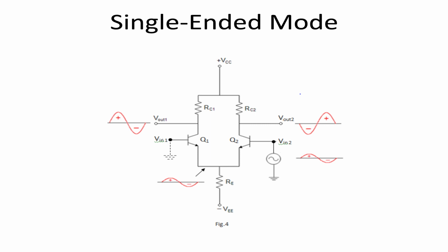The output is always equal to the multiplication of this capital A, that is the gain, and the difference between the inputs, given as V1 minus V2 or V2 minus V1, as we have two inputs at the op-amp. So, whenever we use this term in this topic, it refers to how we can apply the input, in how many ways we can apply the input.